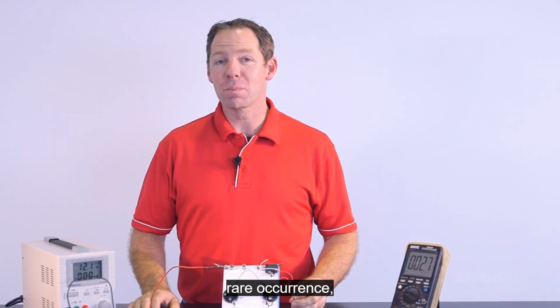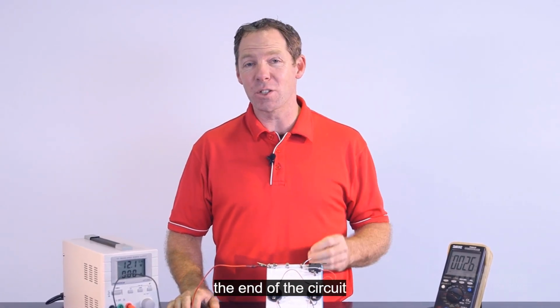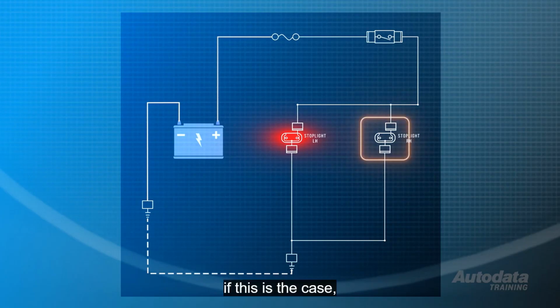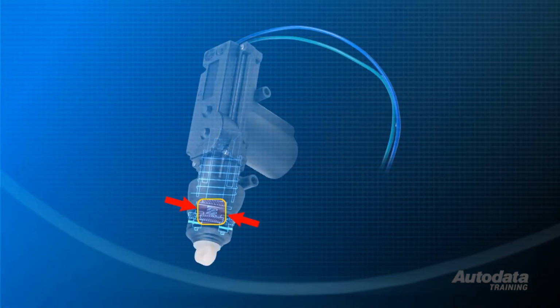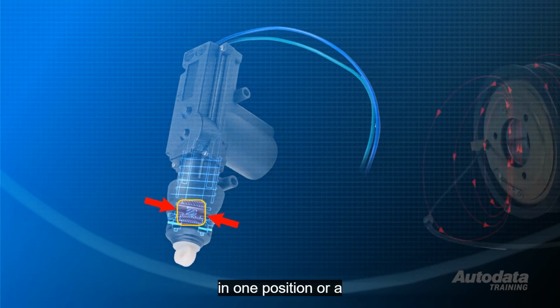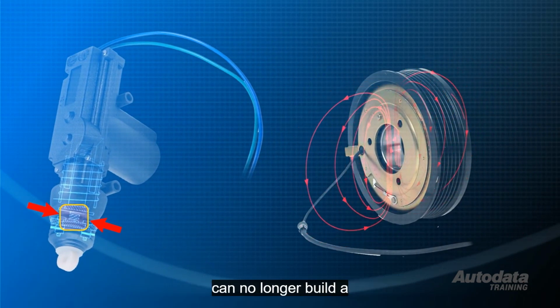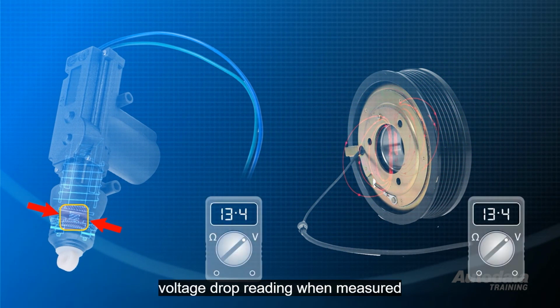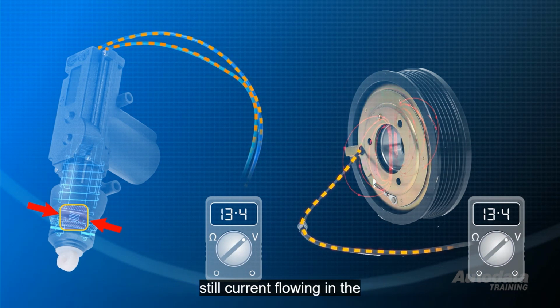Although a rare occurrence, sometimes we may get to the end of the circuit and see no abnormal voltage drop on the meter. If this is the case, the fault most likely lies in the load. A mechanical failure, such as a solenoid that is stuck in one position, or a shorted AC compressor clutch that can no longer build a sufficient magnetic field to engage, will result in a normal voltage drop reading when measured across the load. This value exists because there is still current flowing in the circuit, even though the load is not operating correctly.